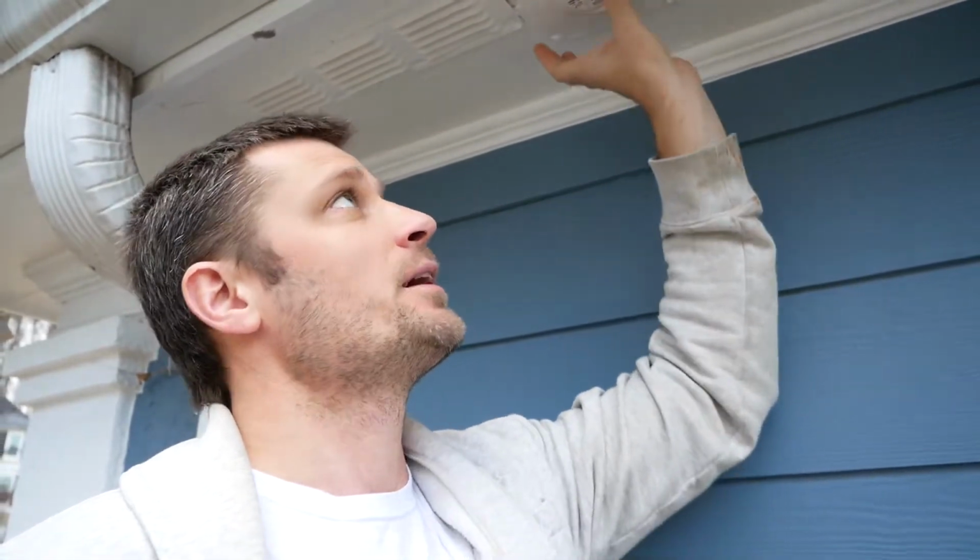Now, another problem we find here as well is a lot of times venting from the inside of the house is best going out the roof. In this case, it's coming out the soffit. I'm not as worried about it coming out the soffit in this case, since it's not going to be the main fan bringing humidity outside of the bathroom. I'm actually going to add an additional fan to that bathroom on the main ceiling. But for that, it's mostly just for that little toilet room. So I'm not as worried about it coming out the soffit.